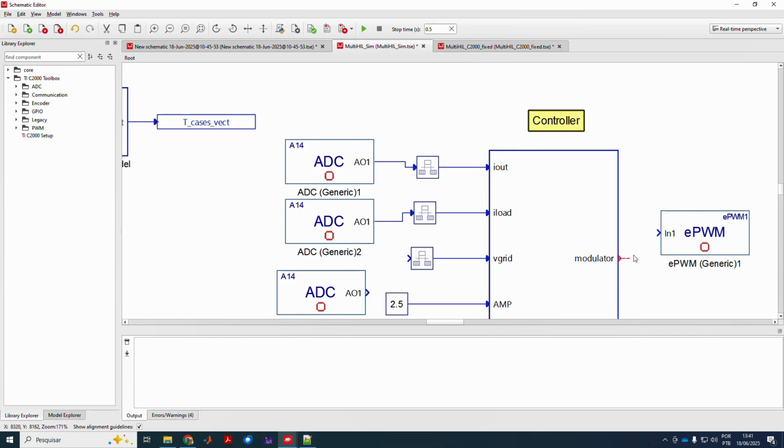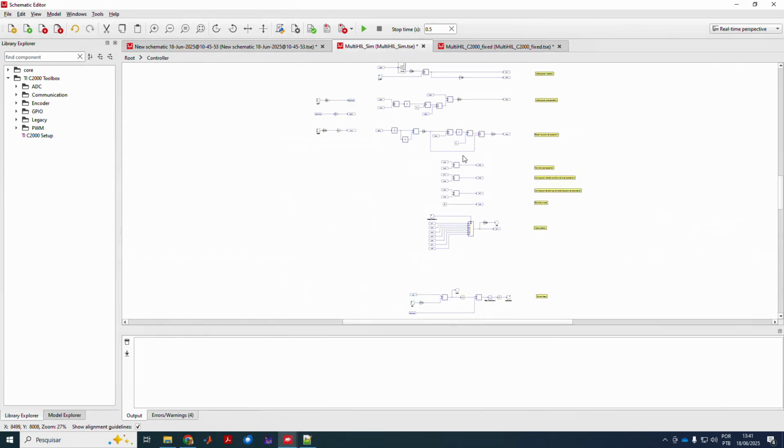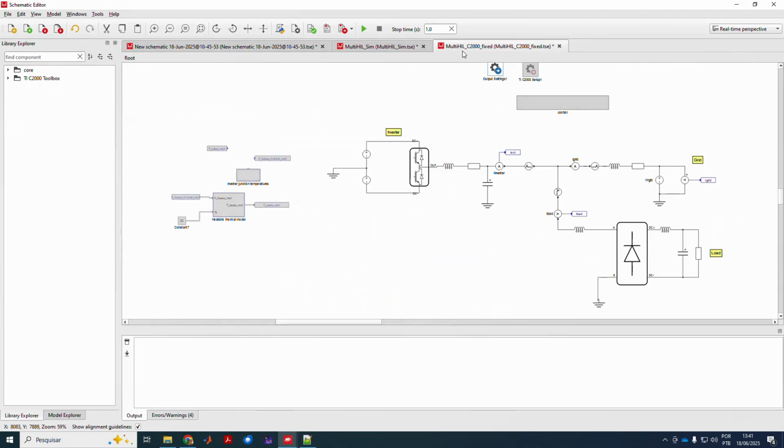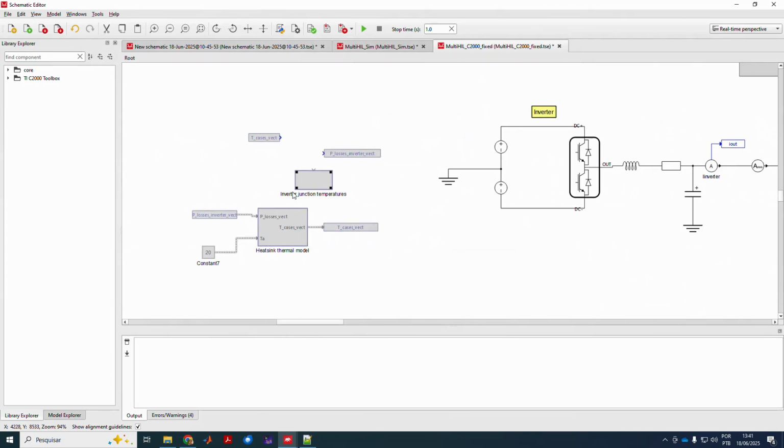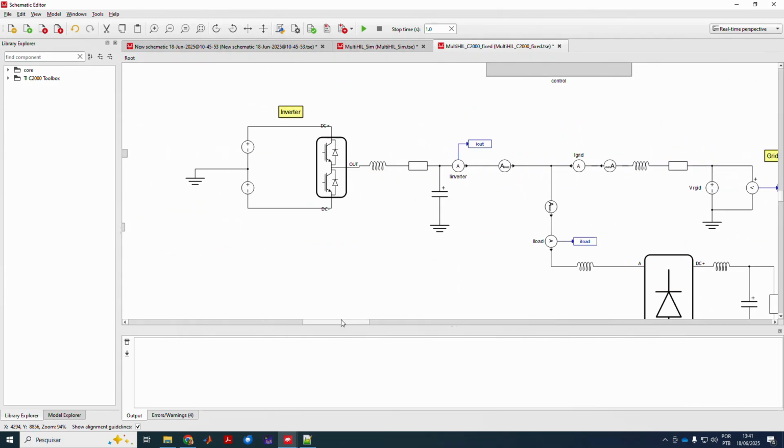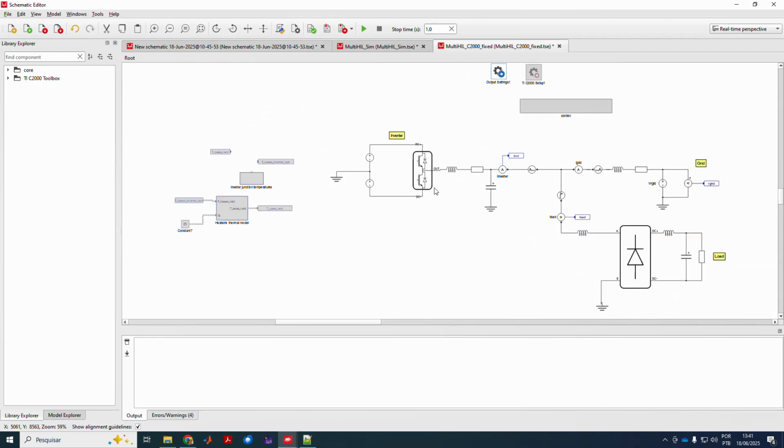Essentially, to generate the code from my controller, I need to make these replacements. My controller is the same, but in order to speed up this video, I already have it here. Moving to this model, I have the same model. I just had to remove the part that belongs to the power losses analysis, because later I'm going to run these power structures in the Typhoon HIL 402.